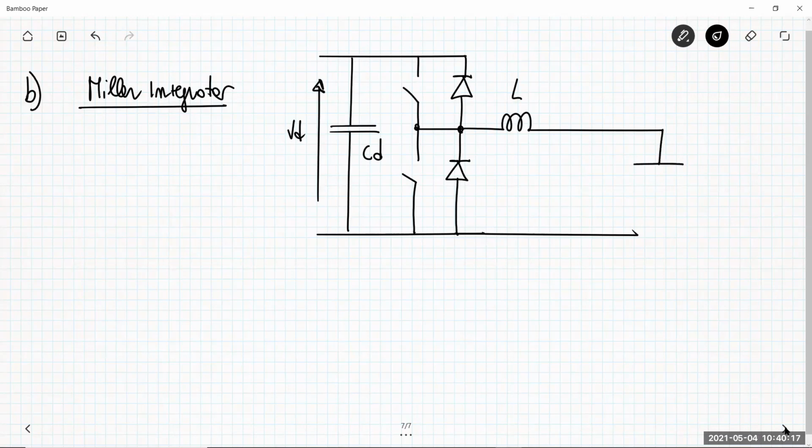Here we have the Piezo injector. Okay, the same reasoning. When we are in the boost operating mode, the transistor TA plus is off, and we are switching the transistor TA minus. Then there is a certain point, after 70 microseconds from the beginning of our discharging phase, in which the boost is no more effective in recovering energy.